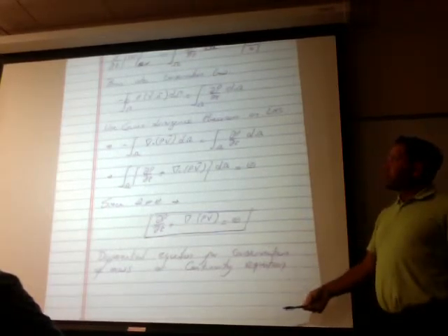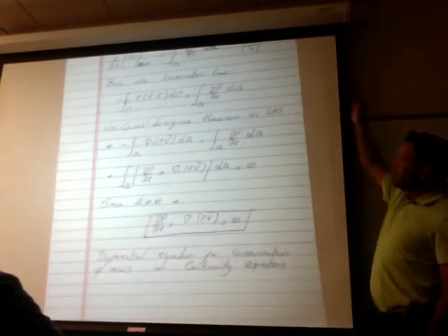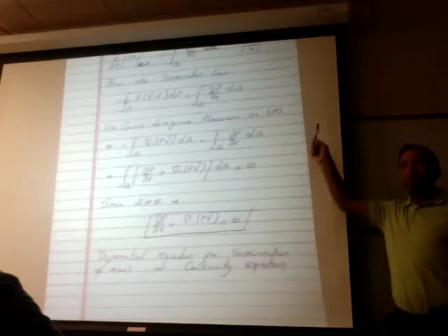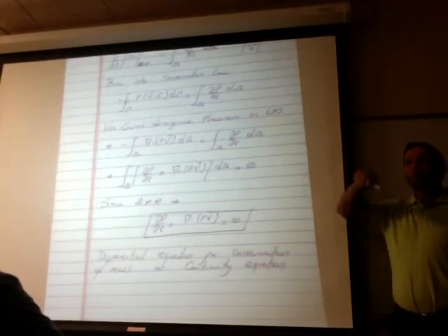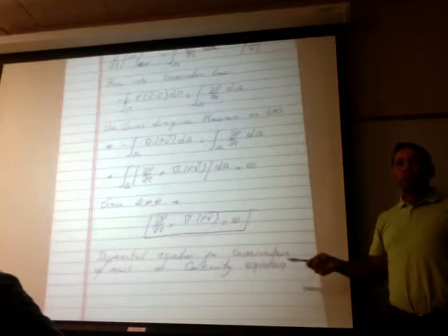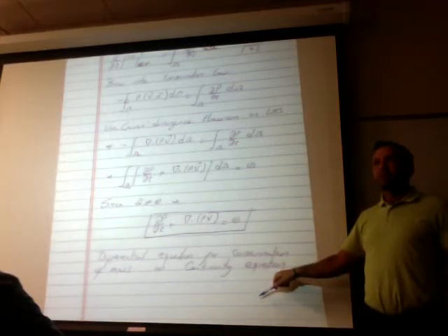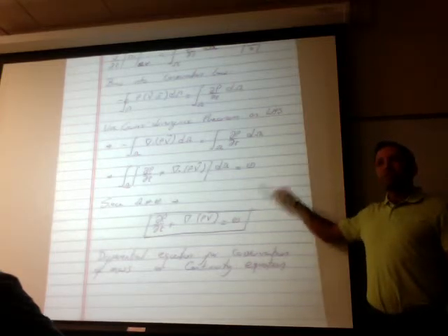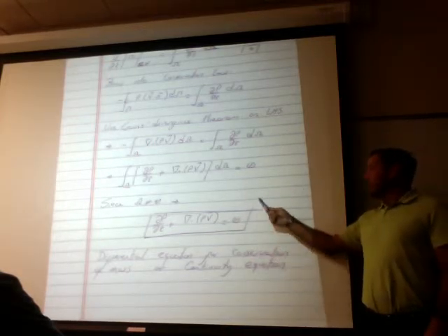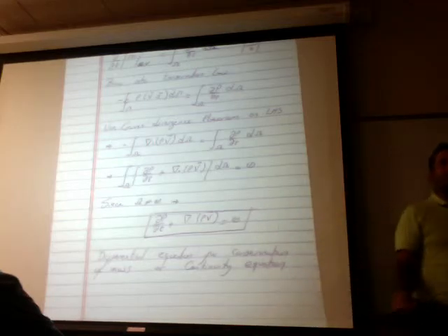In the Navier-Stokes equation system, we do the same exact thing. We apply conservation, but instead of conservation of mass, we do conservation of momentum, Newton's second law. And when we do conservation of momentum, we end up with 3 additional equations. Now we have 4 equations for 4 unknowns: density and the 3 components of the velocity. And there we go. So then we can attempt to find either analytical or numerical ways of solving for these.